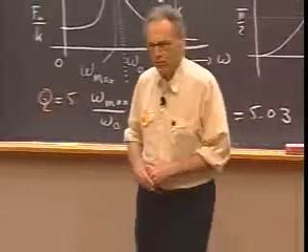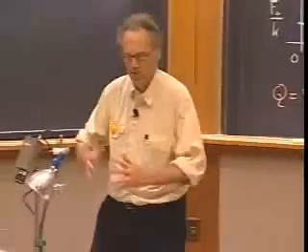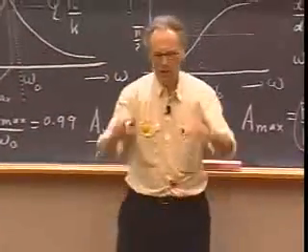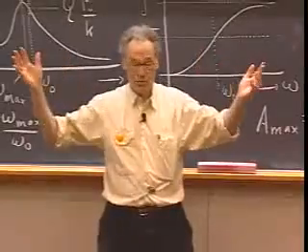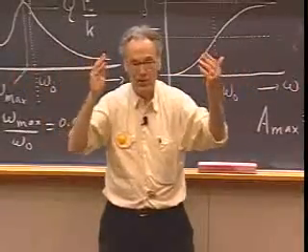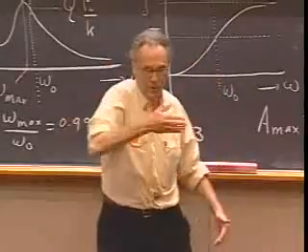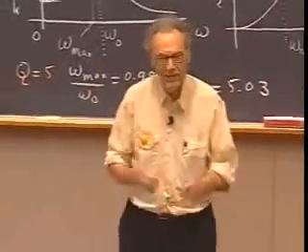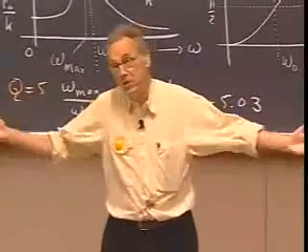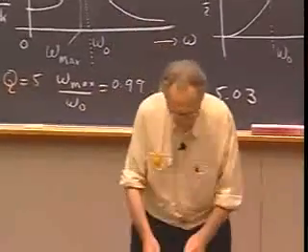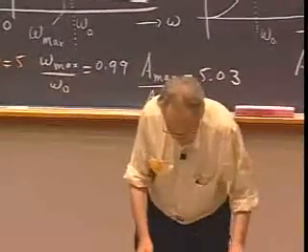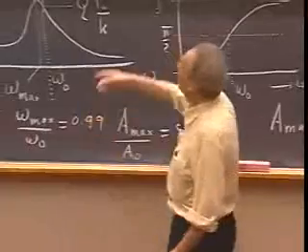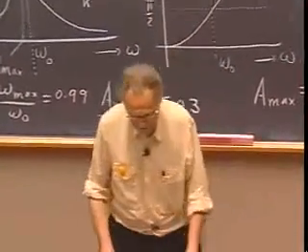You've seen footage lately of the storms, three storms in a row. And you must remember sometimes that you saw a traffic sign. You see a pole, and then a traffic sign. And even though there's some kind of a crazy wind going, the traffic sign goes like this. All resonance frequencies. It can even break. Even though the wind appears to be relatively steady, the wind generates, in a way, a whole spectrum of frequencies, and this traffic sign picks out the one that it likes the most, and then it goes nuts at a frequency that is a resonance frequency.